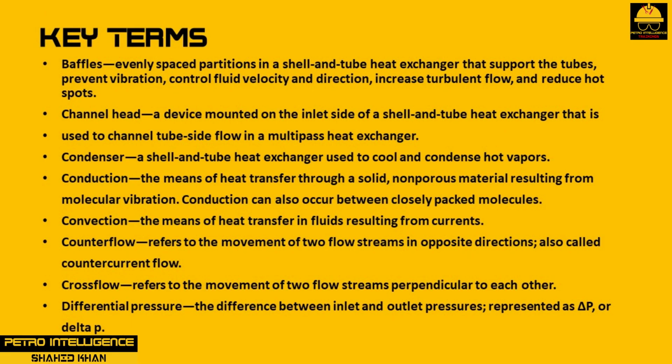Baffles are evenly spaced partitions in a shell and tube heat exchanger that support the tubes, prevent vibration, control fluid velocity and direction, increase turbulent flow, and reduce hotspots. Channel head is a device mounted on the inlet side of a shell and tube heat exchanger that is used to channel tube side flow in a multi-pass heat exchanger.